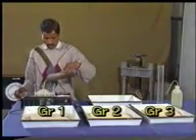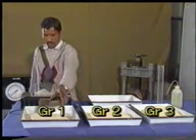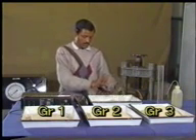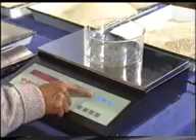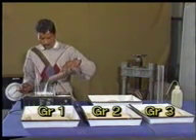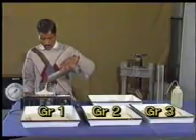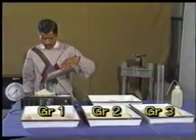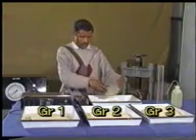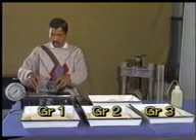For this test, measure 200 grams each of standard sand of grade 1, grade 2 and grade 3. Place the measured quantity of each grade of sand in the enamel tray.